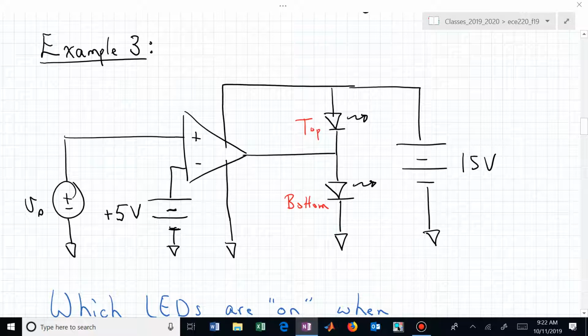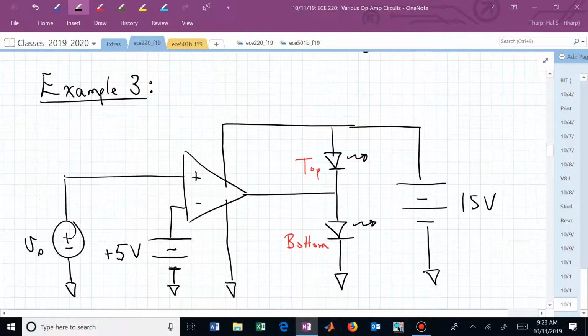Now what you don't want to get too forgetful of is, wait a minute, the way he's drawn this, that op amp really only has things going to the input pins and things going to the supply pins, nothing connecting the output of the op amp back to any of the input pins. There is no feedback here. Let me change color so it stands out.